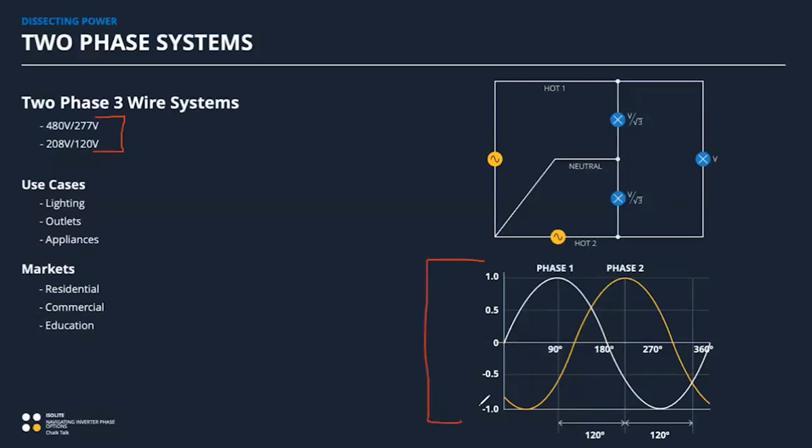And so in this situation, some places around the United States, this is fairly common, where there may be a 3-phase power system on the pole, but only 2 are brought to buildings. That's kind of a historical vestige that doesn't really exist in new construction anymore. But where this does come up is if you're going to be directly driving things like 277 volt lights, and not a sub panel, but you have a 3-phase system and you need enough power to drive 2 different phases of it, this is the thing that you would then use in those applications.